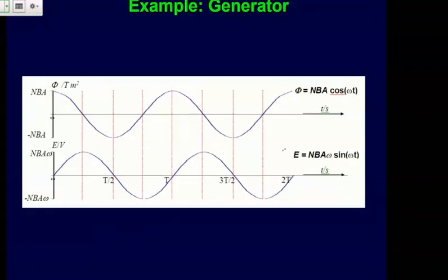So you can see that relationship there. And basically it's just the same relationship between a sine and a cosine. So you can just sort of see that, for the EMF, you get this maximum of the EMF when the slope over here is sort of its steepest, right? And then when the slope over here is 0, you get 0 EMF. And so these are just related again, because this is the derivative of this function over here.